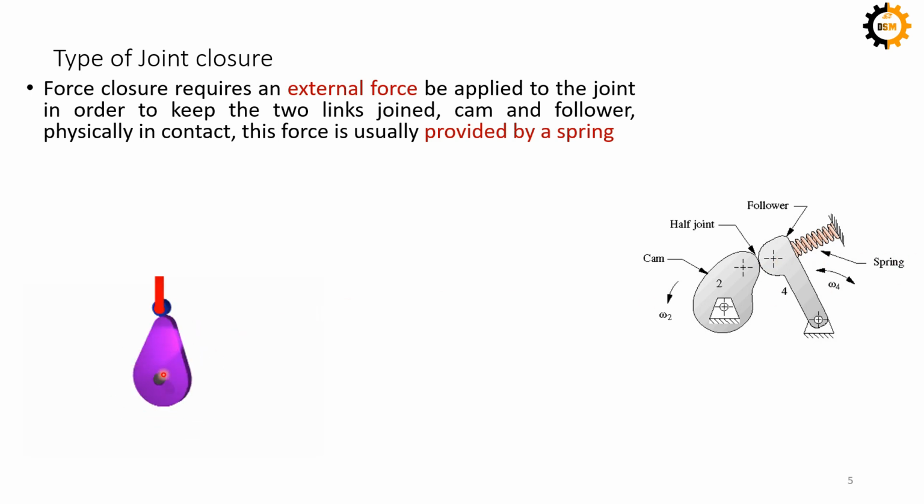So you can see that this is one effectivity of this spring. In this figure, you have a cam which is rotating, and a roller follower moving up and down, so it is translating. At any point, the follower is falling under the action of gravity. But if I show you another figure, this one, try to observe the difference. I would like to know what difference you are observing in the two examples, and what is the reason. The hint is that it has something to do with force closure.